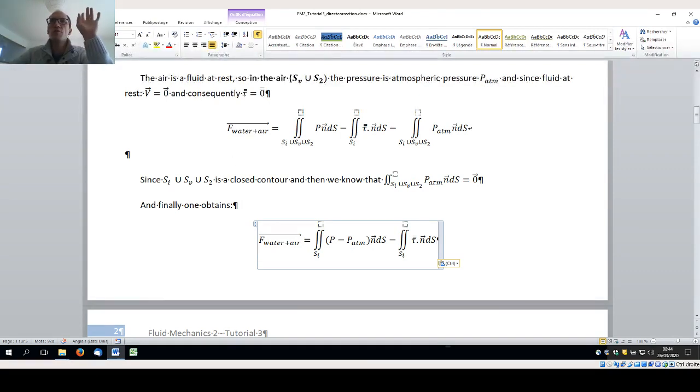This should be very clear, because this is usually the first step you need to follow: to be able to express the force exerted on an object in any kind of condition. It's always expressed something like this, where the force is a contribution of pressure and viscosity, and here you have only the surface in contact with water, named SI, with relative pressure and the viscous stress tensor.